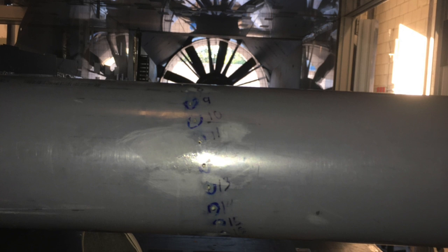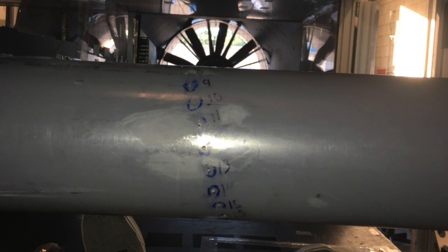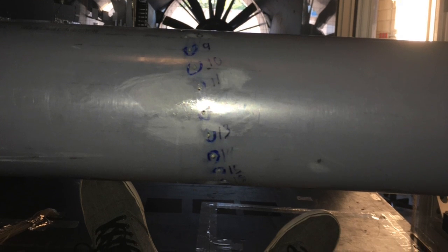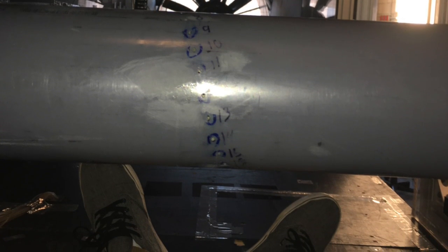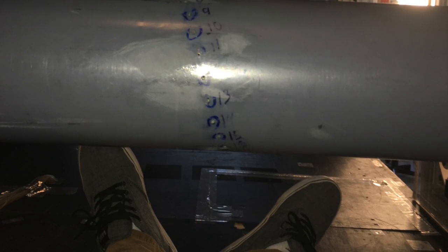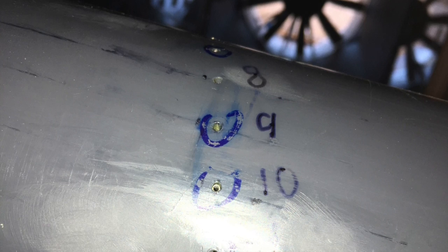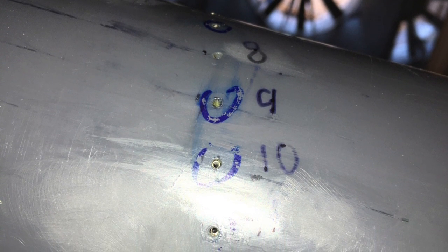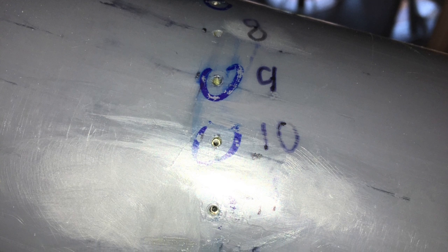Before testing began, ambient conditions were collected via a virtual weather station present in the control room of the wind tunnel. This data was imported into LabVIEW to calculate density for the current conditions. The wind tunnel was run at two different RPM values, 310 and 650, which correspond to 13 and 23 meters per second, respectively. Once the flow in the test section stabilized at both velocities, data was taken.